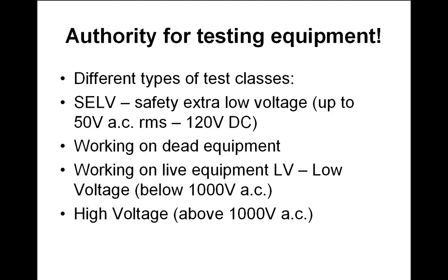And then obviously high voltage is above 1000 volts, but you need a completely different set of skills to deal with that. So when you go to a substation or to a transformer station, all you need to do is be near a transformer that is dealing with high voltages. And if you are a good conductor down to earth, you might get a spark that goes right across half a meter, even more, and might kill you. So it's very, very dangerous once you get into the high voltage realm, above 1000 volts.